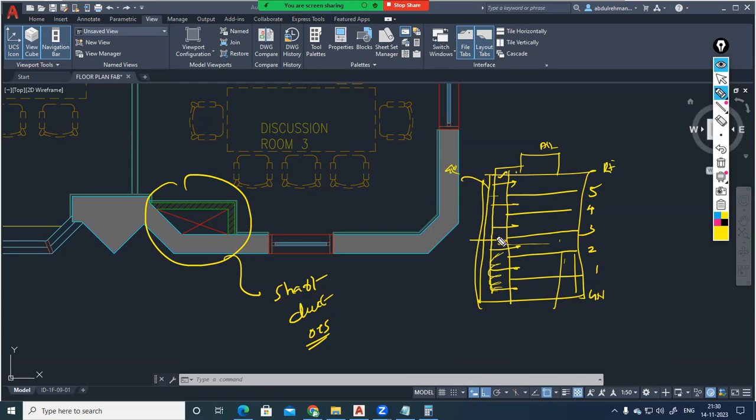So that will affect the performance of your air conditioning machine. But if it is open to the atmosphere, that is called OTS, open to sky region. OTS means open to sky. So if the top side of the shaft is open to the atmosphere, then the rainwater will be entering inside, right? If rainwater is hitting the surface of the AC machine, what is going to happen? These are IP protected equipments only we are proposing on the roof side. What is IP protected? Ingress protected. IP has a separate number.